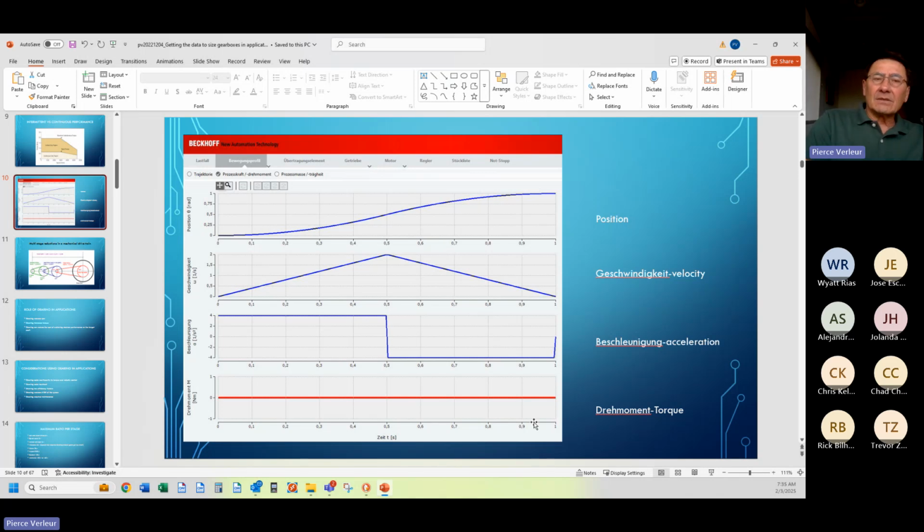Now, wind acts very similarly to friction. So obviously in this application, there was no significant amount of friction in moving the load, probably on some very nice ball bearings and wheels, and therefore not a significant difference between accelerating and decelerating. With a high coefficient of friction, it would resist acceleration and it would assist deceleration. Therefore, this horizontal constant torque curve would be higher in the first half and lower in the second half of this positioning move.